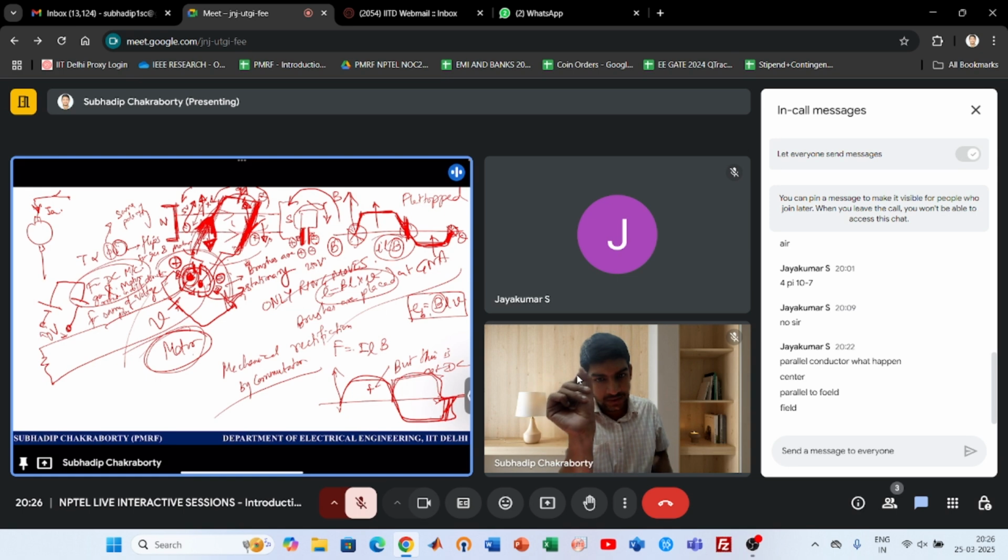Wherever it was positive, the load's positive terminal still gets the positive conductor. Whichever conductor came here gave the positive supply to the positive of the load. So the load feels it is still DC, right? Brushes are fixed, right? One brush sees one polarity. But the conductor inside the machine sees two different directions in one cycle of rotation. Do you get my point or no?